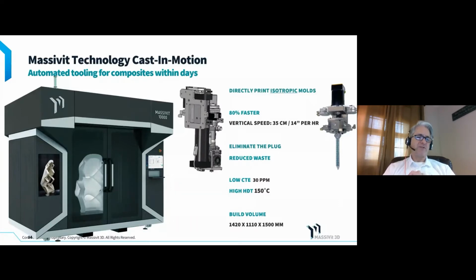So we have examples where you can literally print a horizontal surface by printing next to the previous layer, side by side, and it's instantly being bonded to its neighbor. The print head on the right is part of a mixed meter dispense system where we are dispensing a casting epoxy. It's a thermoset 3D printing process.